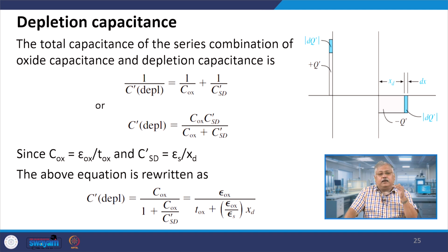Depletion mode device is when you have given a gate voltage, your flat band has actually crossed, and your applied gate voltage is positive for an N channel MOSFET, P type substrate, and it is not large enough to be going to inversion. So, it is between flat band and inversion, you get me point. So, the applied voltage which you are giving is between flat band VFB and VTN, it is between these two, then we have the depletion capacitance.